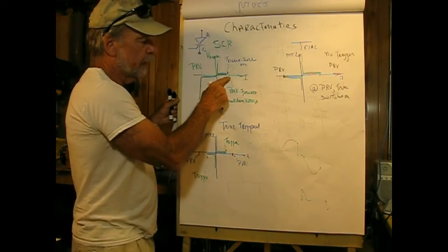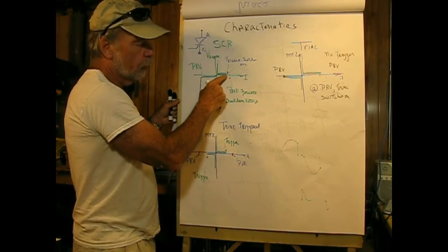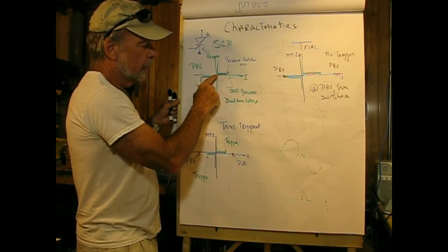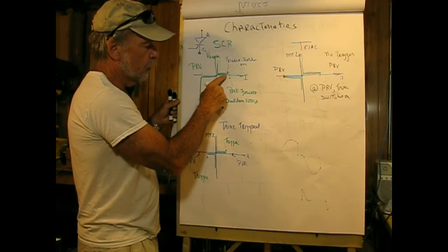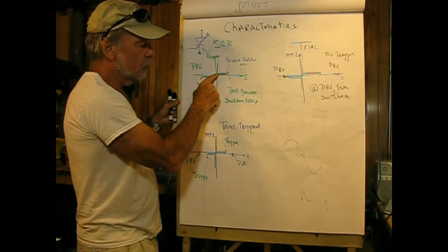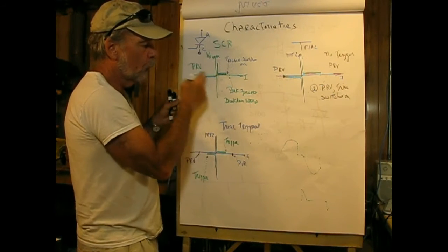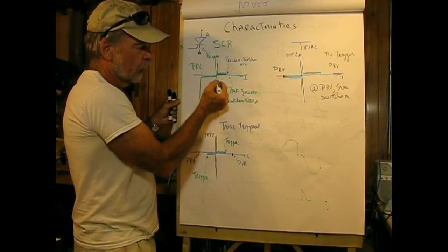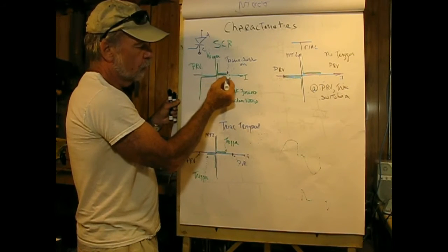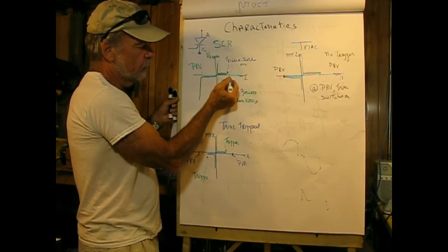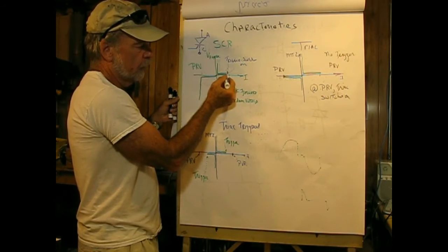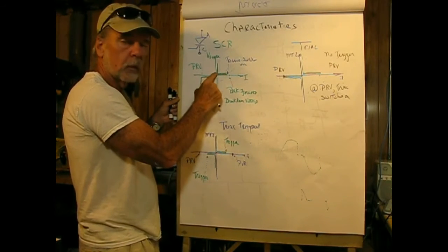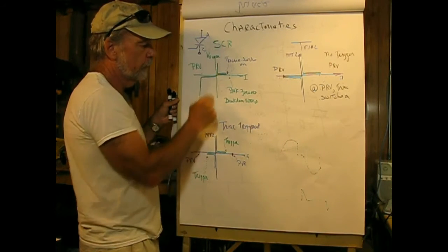Now, if this is the peak forward breakdown voltage, and we're going to trigger before we get to it, what we would see is that the voltage of the input would follow this point until the trigger, and then it drops back close to zero, and then can rise in accordance with the current flow through the device; as the current increases, the voltage drop across the device increases too. So here we see this switchback. Say with a peak of 170 here, or a peak of 200, maybe this is going to be 150 volts where it triggers. When it triggers, the voltage across it drops close to zero. That's this guy. And then as the current increases, it can increase slightly with that.